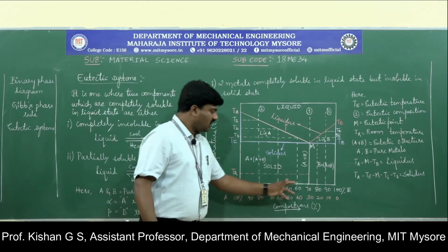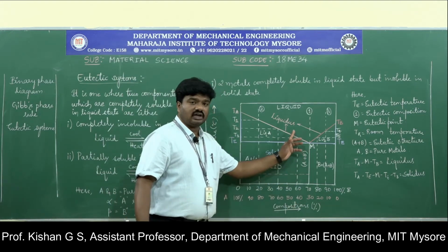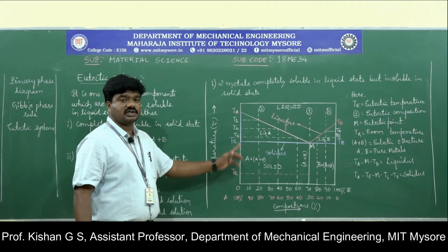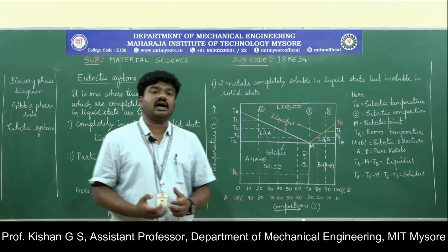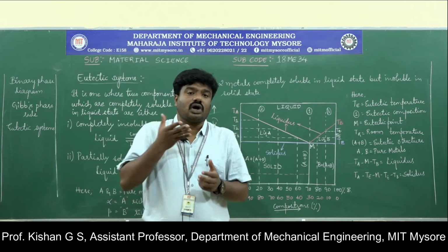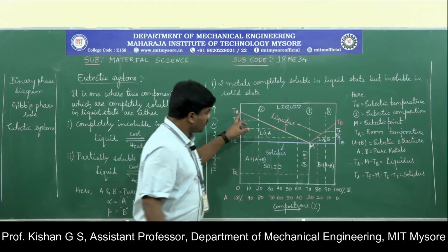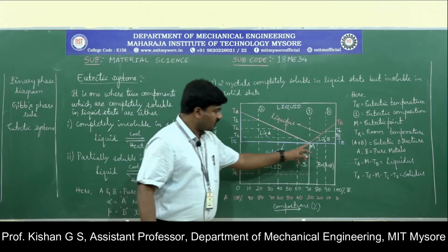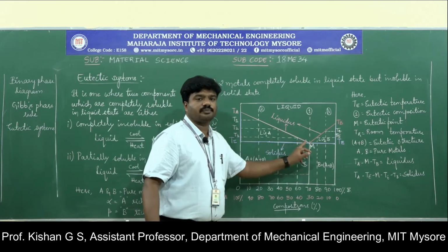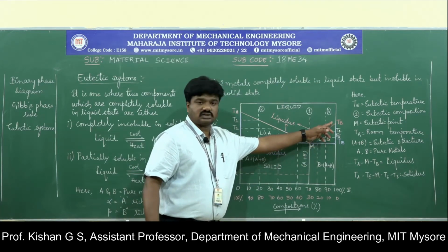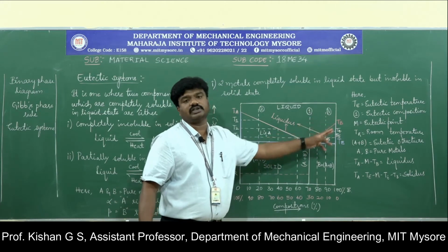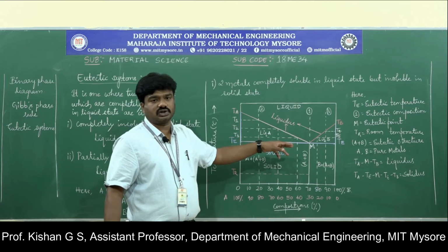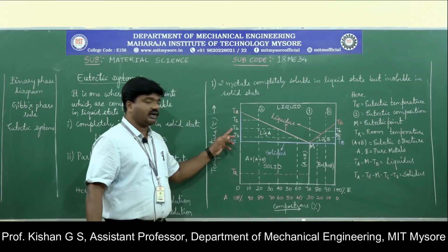So if you draw a vertical to the liquidus line, the temperature is considered to be T3 degrees Celsius, which tells us that the solidification process is almost over, and the temperature is still reducing. At a particular composition M, it is a point where TB, the melting temperature of pure metal B, tends to reduce to form a solid solution. So this is the consideration of T1, T2 and T3.